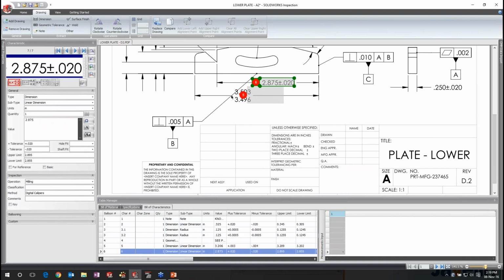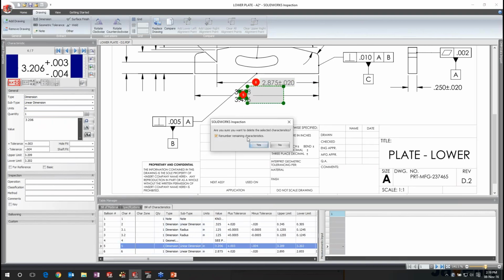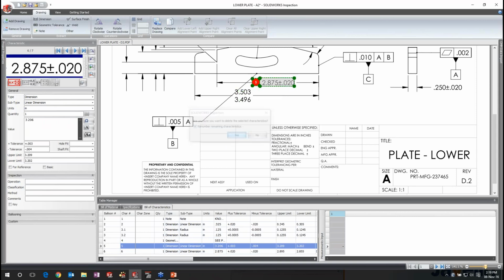And we can see here that, we saw in the preview that this one actually just shifted over or moved. So we can just delete that, or actually this one was deleted. This one moved up and we didn't have that as an item, so we can just simply come in and say no, delete that characteristic. We have the option to renumber or lock numbering, just as you saw Sam do earlier. All right, so you can see because I did the auto renumber, I didn't lock the balloons, it replaced the old number 5 with this one.